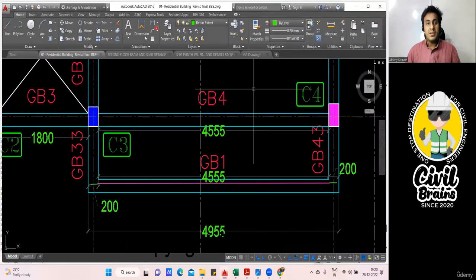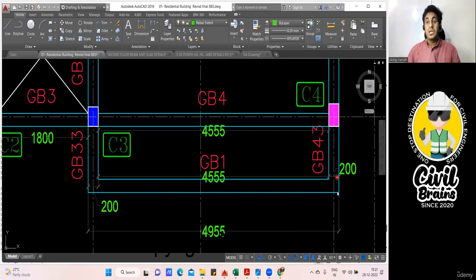And then this will be your development length like this. This will be resting in the beam, okay? This is a development length. You can find this, no? That's it. Now you add all the lengths, you'll get the cutting length. Top I did. Similarly, you do the bottom bar. Very simple, you can do that, no? One case study we learned: if there is a beam coming, you have to deduct the beam cover, not the column cover there.